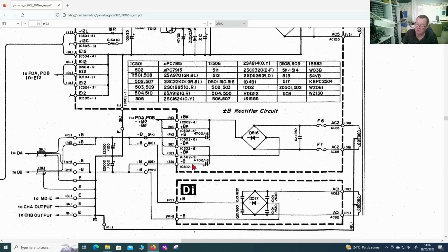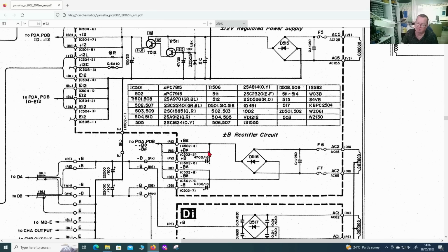The reason they've done this, I'm sure, is so you don't have to have some more big 100 volt capacitors. Effectively, they are just putting this one between the 87 and something less than 16 volts more, and between the minus 87 and something less than 16 volts more negative, okay? I think that's just to make smaller components, basically, less space.